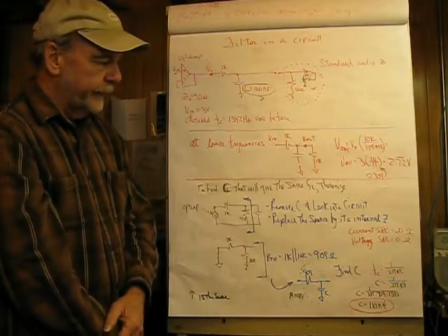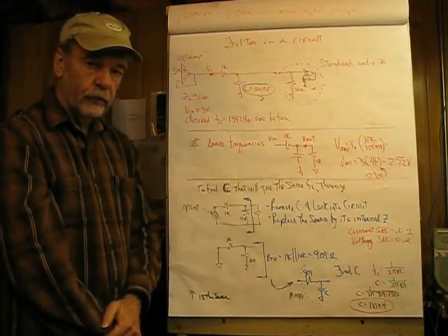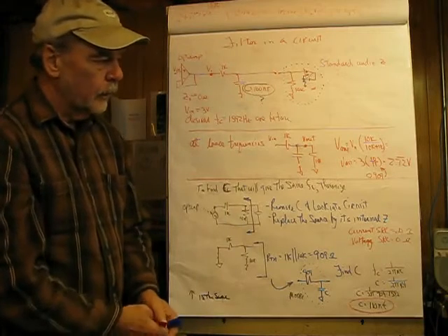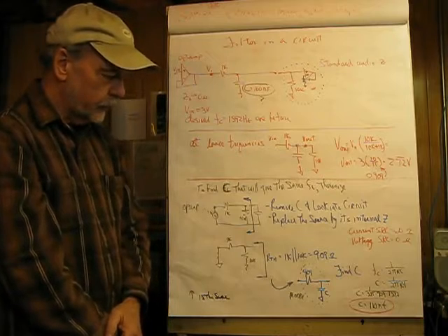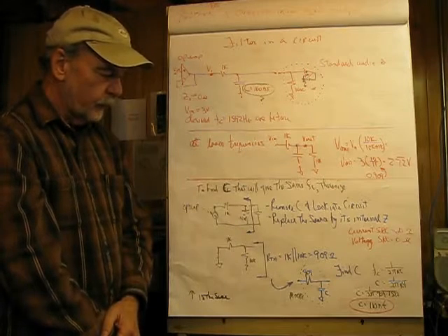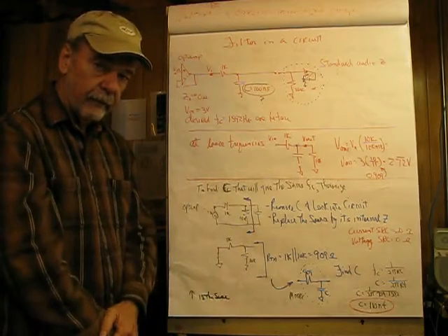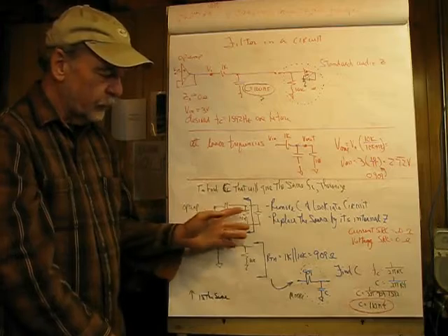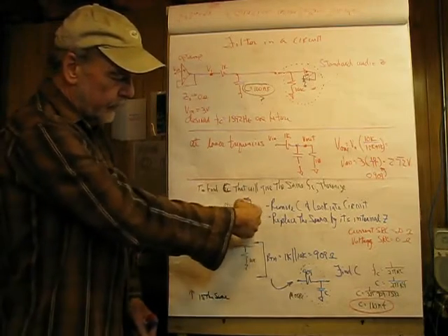Now we have to find the value of C here, and we're dealing with a different resistive component, 909 ohms compared to 1K. So that's going to change things. And to solve this, one way at least, is to bring in the Thevenin equivalent circuit. And what we're going to do is disconnect the component of interest, which is the capacitor, and look into this.